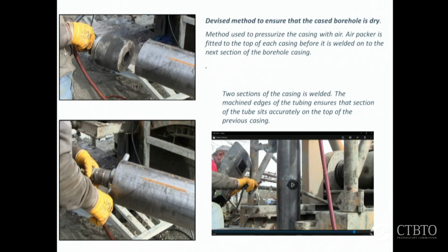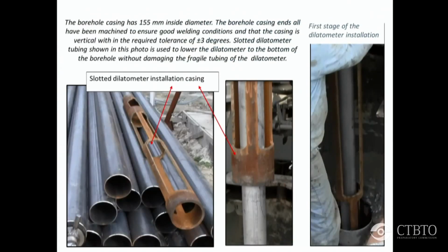It took about a day and a half to install the 150-meter borehole. Now, each section of the borehole is about 8 meters long, as you can see there. And at the bottom of it, we decided to install the dilatometer. The dilatometer is an extremely sensitive device. It has literally 2.5 to 3 millimeter thick casing.